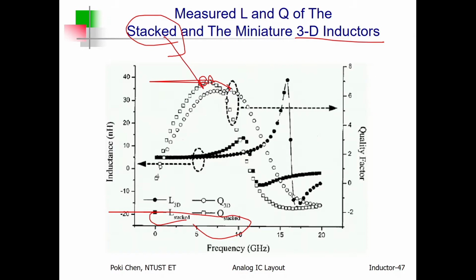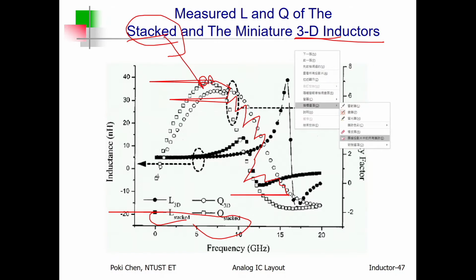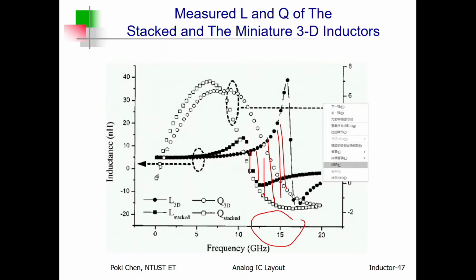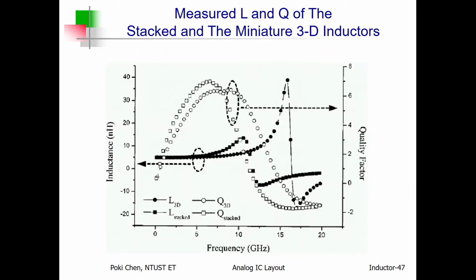However, again, for higher frequency band, actually the Q factor is improved for 3D inductor than stacked inductor. And how about the inductance? Again, here, you can see the 3D inductor is much better than stacked inductor for such kind of high frequency band. And also you can see the self-resonant frequency is much higher from here to there.